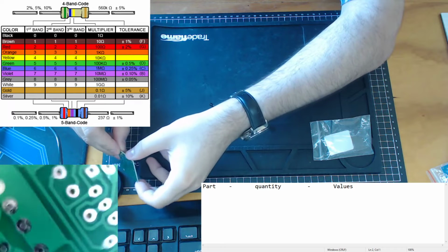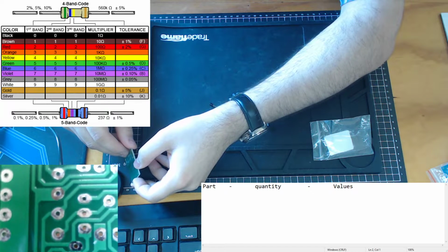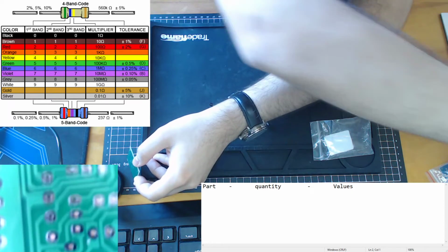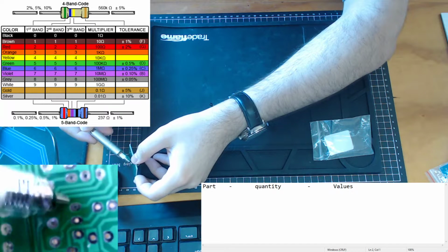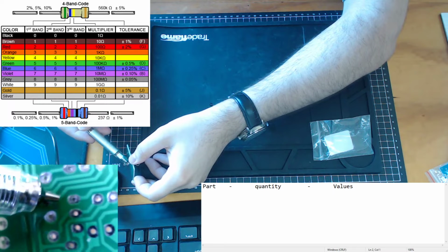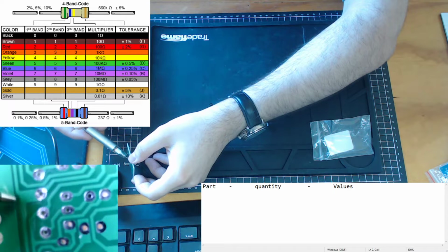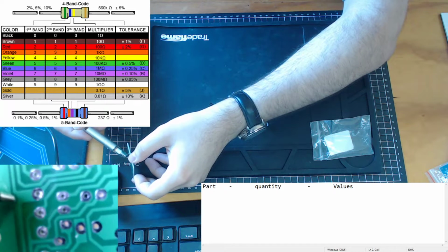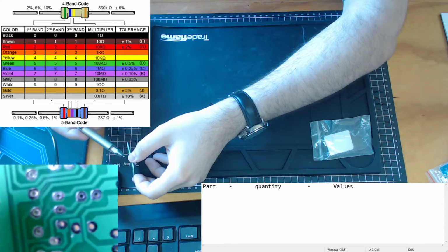On the other side of the circuit board, we have all these metal contacts. Let me just get a high-tech pointing implement over here. Over here we see these exposed areas of the circuit board, which are these metal tabs. When we solder, we're going to be able to solder to those metal parts. Then we have these other areas that are different shades of green, where there is copper underneath providing connections on the circuit board, but they're covered up by a layer of lacquer.